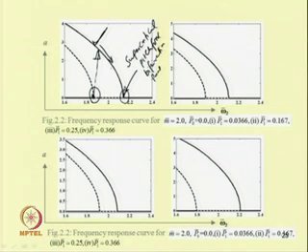Similarly, by changing the system parameters. So, for example, in the first case, by taking this non-dimensional amplitude of dynamic loading equal to 0.0366, and in the second case it is taken to be 0.167, that means the amplitude is increased. So, one can see that when the amplitude is increased, the response amplitude of the non-trivial state also increases, and one can study where the pitchfork bifurcation takes place.